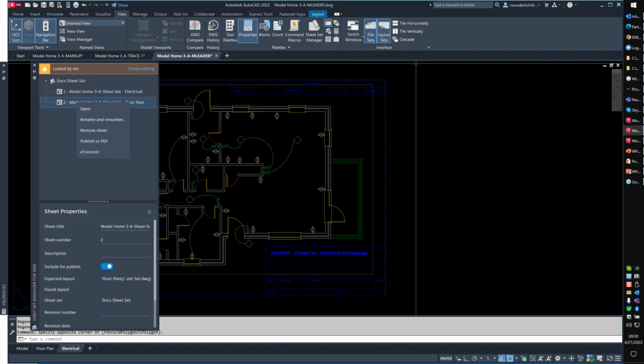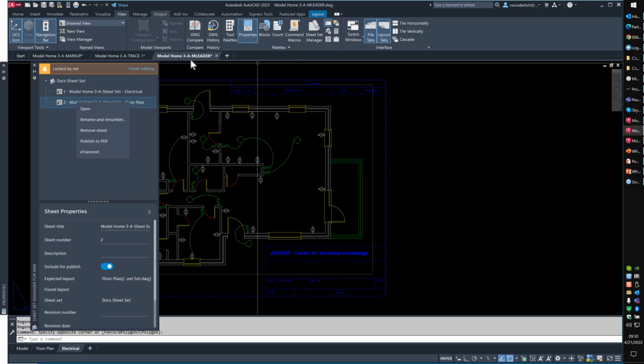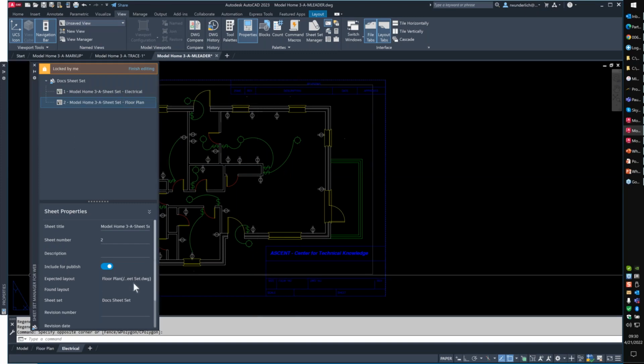Would you be able to make edits in an offline DST, put it on BIM 360 to get around some of the lack of editing? Yes, you can do that. The one that I have on my desktop is a copy of the one off of the Docs. Copied it local, made my changes, and then I can put it back up. Can you copy it back locally to edit the other fields and re-upload? Yes. Just understand that this is a light viewer version. Other than that, it performs exactly the same.